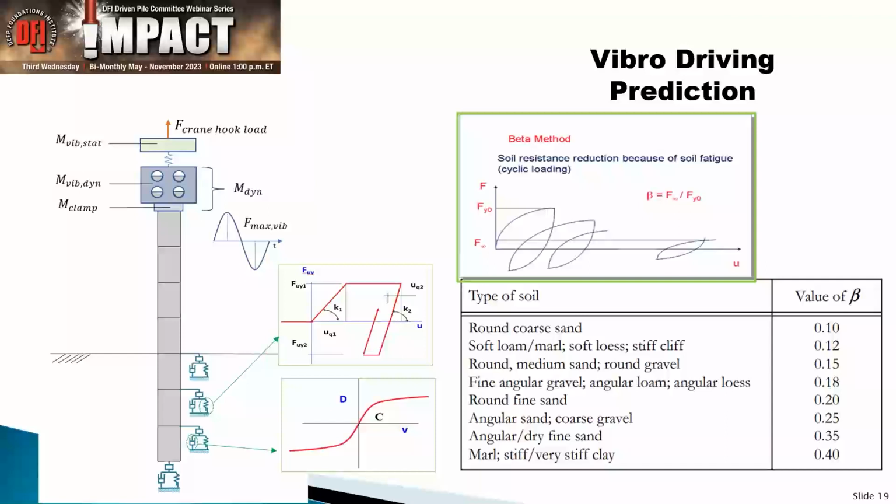So in no time, you have thousands and thousands of cycles, which means that the soil fatigue that you have to address to some extent with impact driving automatically becomes a fact of life and something that you can simplify.